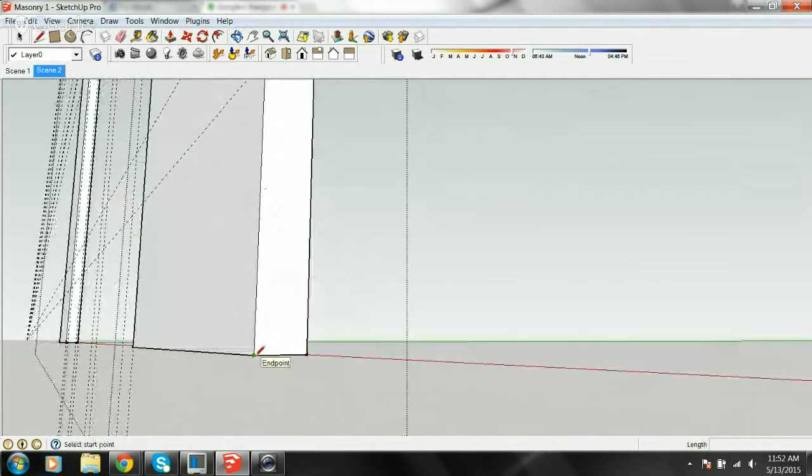In the architectural world, a standard size brick is 3 bricks is 8 inches tall. So 9 bricks is 24 inches. Well, I'm not going to get that detailed in this particular model for this current video. I just want to show how we can put the mortar lines in. So that's like 2 3/8 or 5/16 inch tall with a 3/8, 5/16 joint. But we're going to make it simple.